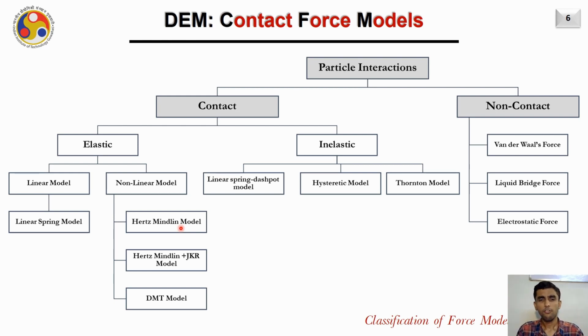But towards the end, we will also be looking at the Hertz-Mindlin plus JKR model, the Johnson-Kendall-Roberts model, which is used for the simulation of cohesive media. Cohesive media are generally those where the particle size is very small and the particles have some amount of moisture content in them, so we have to use contact models that can model the cohesiveness amongst the powder particles. The Hertz-Mindlin with JKR model can model this cohesiveness.